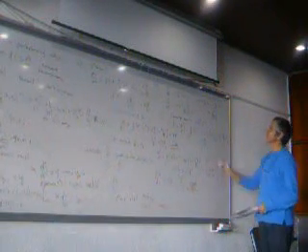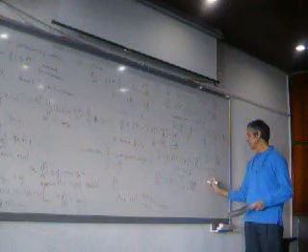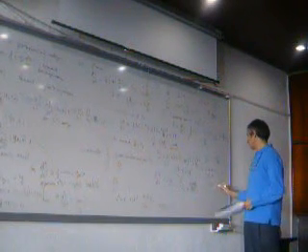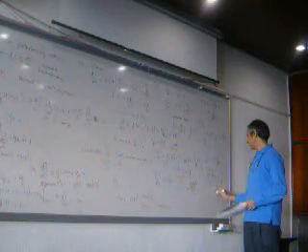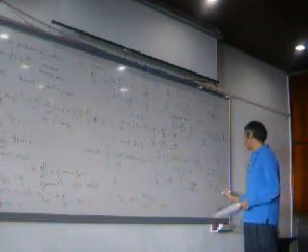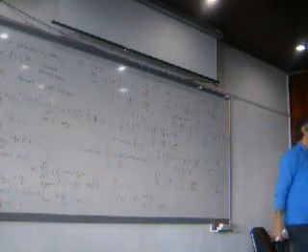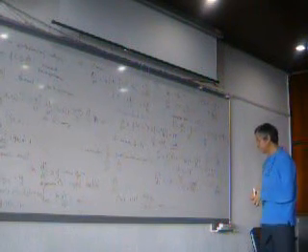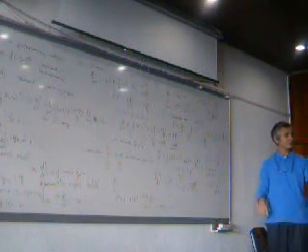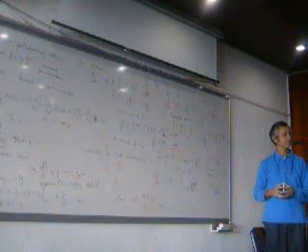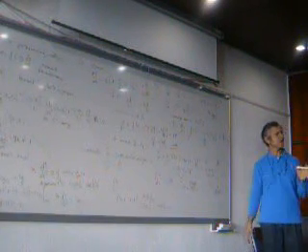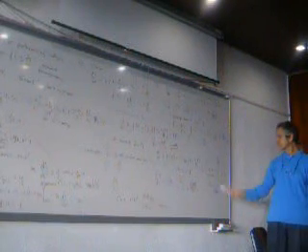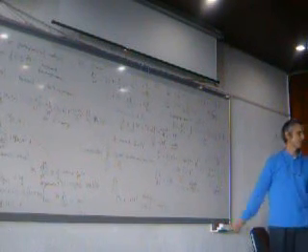So the point 0, 0, this equilibrium point, is what? Stable. It's a borderline stable through repeating? No, no. You don't have repeating 0 here. If you had repeating 0, it would be unstable. This is not the borderline stable. We use that term when you have pure imaginary roots. This is stable. Okay.